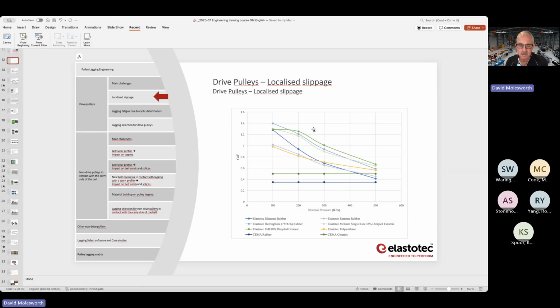If you introduce different speeds, then the graphs change. So that's when it becomes three-dimensional. You can see the reality of friction is nothing like the fixed figures that CEMA use. Somebody obviously has done a lot of work in the past and worked out some conservative numbers that you can use and be quite safe that you're going to be able to transfer the power. Yeah.